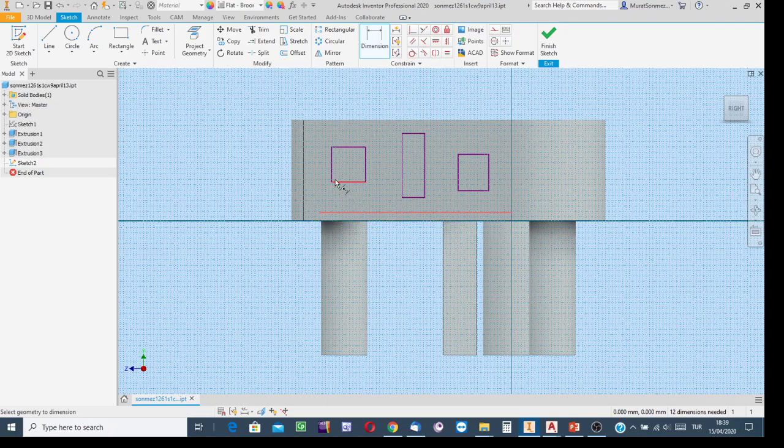click to the lower boundary of this window opening. Say that distance is to be a standard distance, say that it is 900. Near to 1 meter. The unit of measurement in this environment, since I selected the ISO template, the ISO metric unit system, is millimeter.